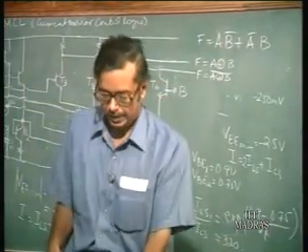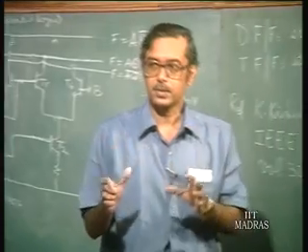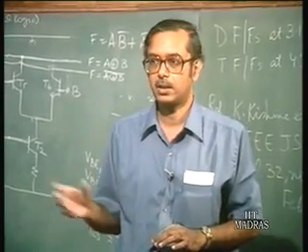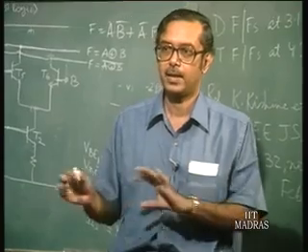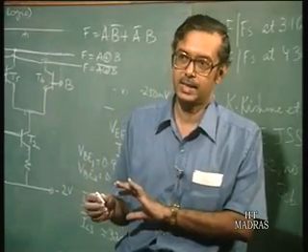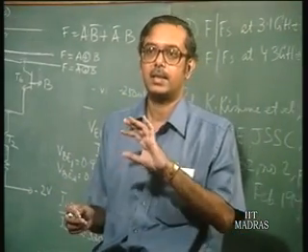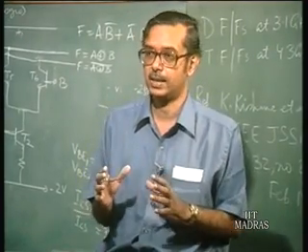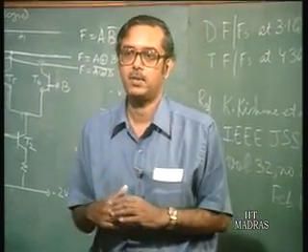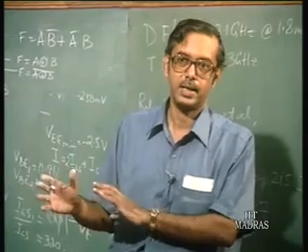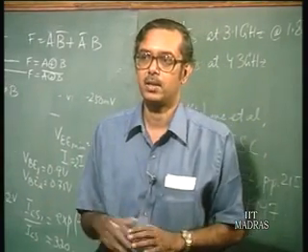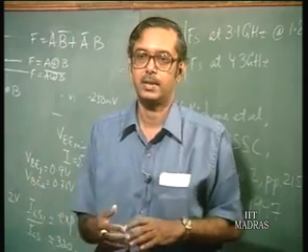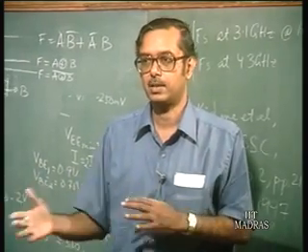So, today we have discussed a new circuit concept, the current mirror control logic, and this is again a variation of ECL gate, and it helps in reducing the actual power dissipation in ECL family of logic gates. There has been a lot of work in this area, and this gives you some idea of the ongoing work. A lot of people are still working on how to reduce the power dissipation.